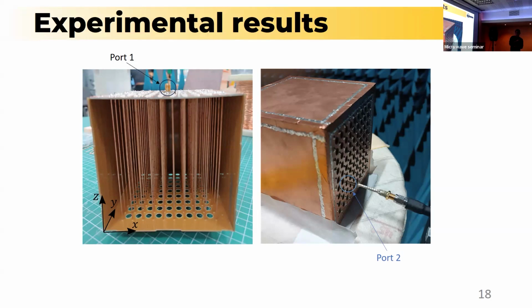It will be scanning our field through some pre-drilled holes, in the transversal section. So the idea to measure the electric field is to measure the S21 parameters at the different holes that we have in our 2 cavity prototypes.